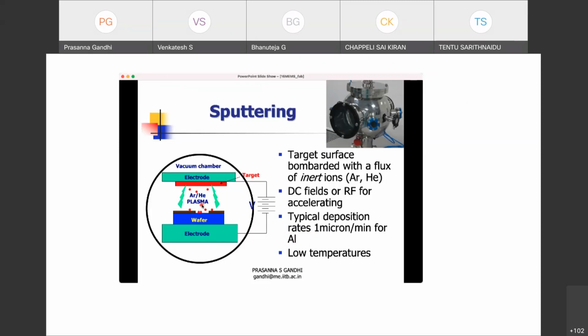These residual stresses are a very important aspect that one has to keep in mind while processing your wafers, to make sure that you get films which are not cracked or subjected to these high stresses. So you may need to follow some annealing process or something like that to relieve the stresses.